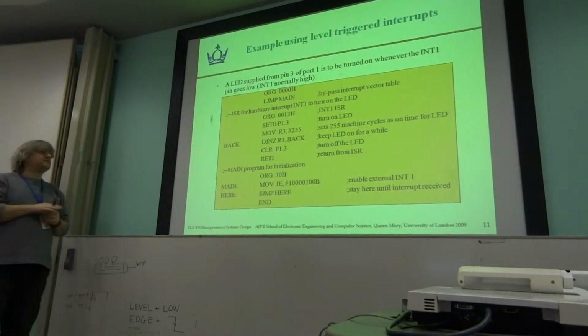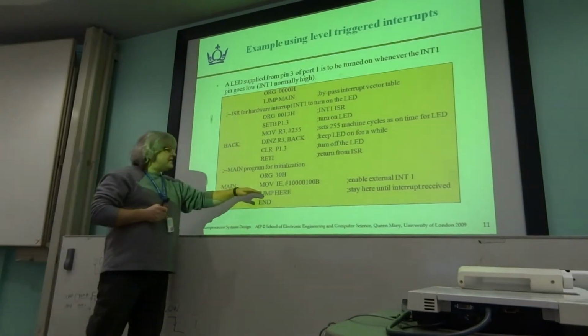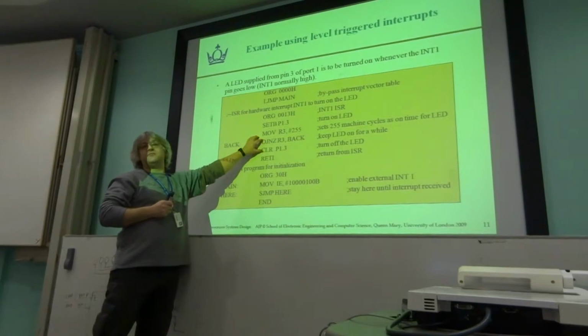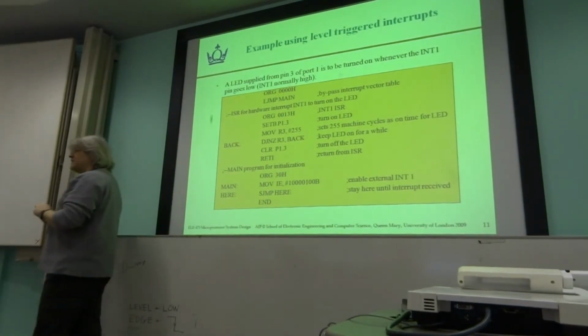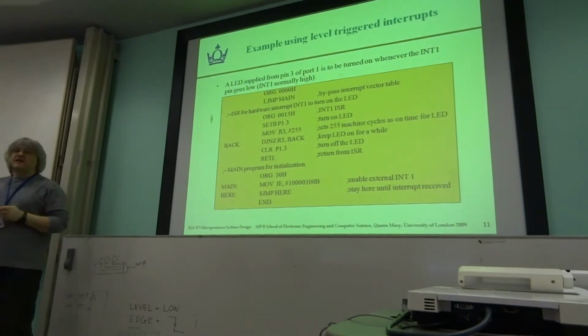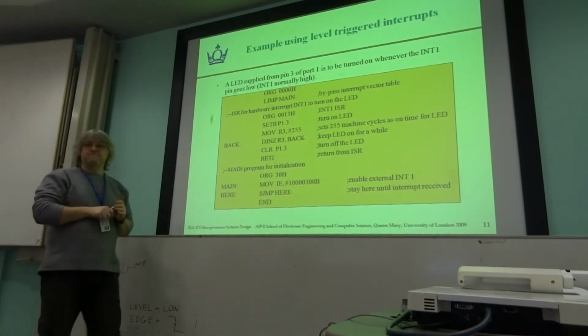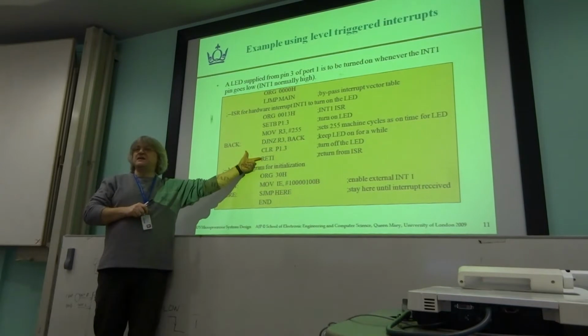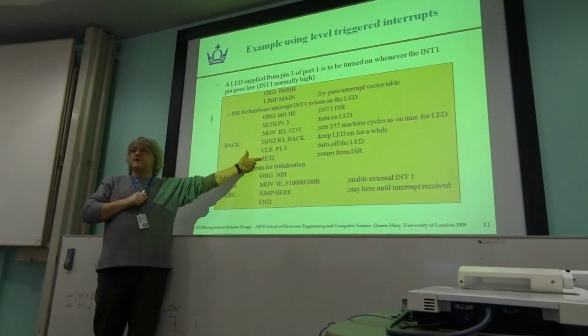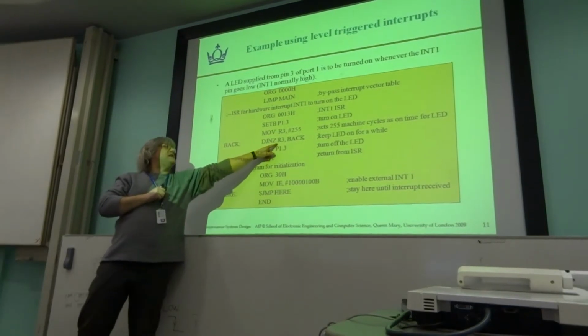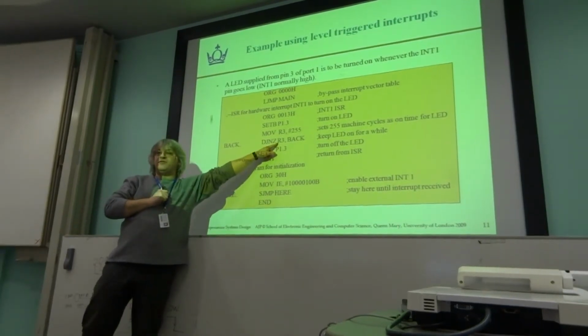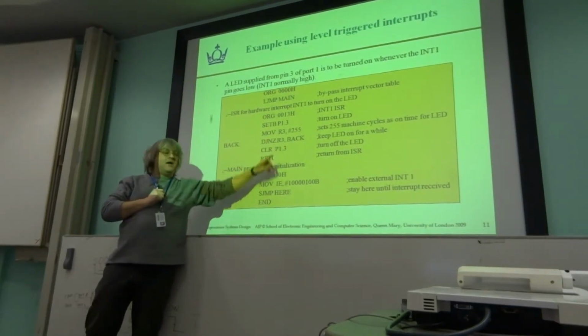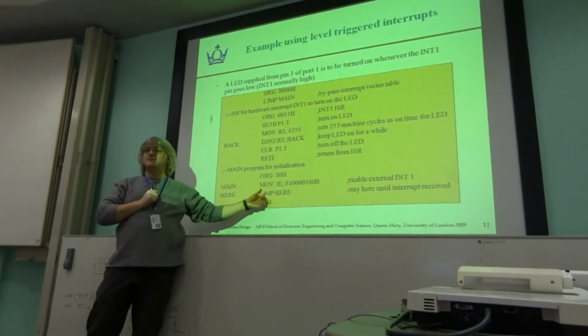I'll say some more things about when we go from the main program into the interrupt service routine. The only thing that happens in terms of the stack is the program counter gets put on it. And when you leave the interrupt routine, what's on the stack gets put back in the program counter. Now, inside your interrupt routine, in this case, I'm fiddling around with R3. If your main program is doing things with R3, we would potentially have a problem.